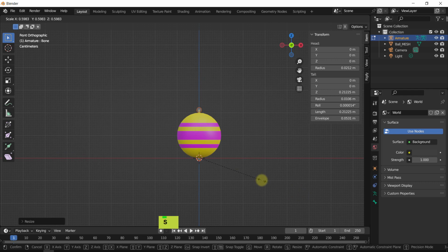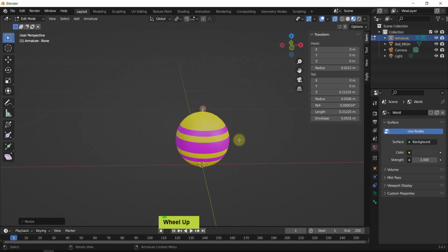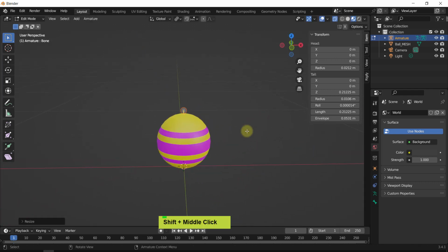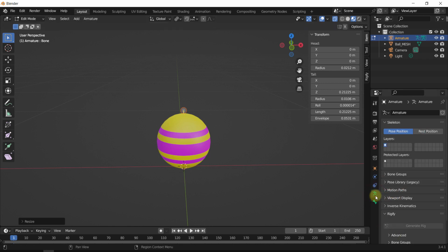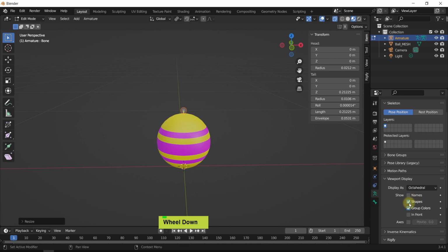Now here we are, and let me stop for a second here and use something that could be really helpful. So it's not there yet, it's not properly sized yet. We can go into viewport display, selecting the stickman, viewport display, and we have various options to deal with this. Now here's one thing that's really important. This is called in front, and the other thing I will use that helps us to work with this is I will turn on names.